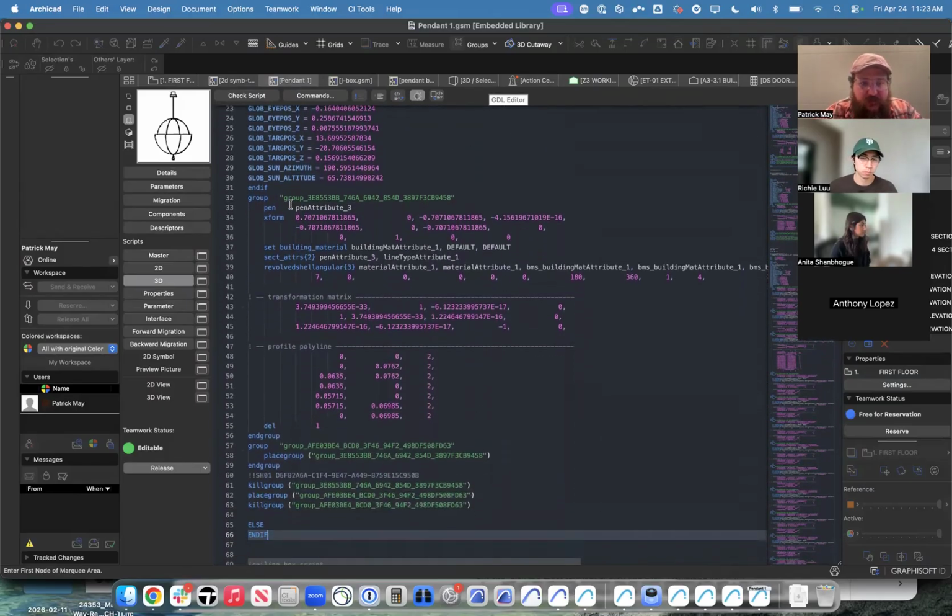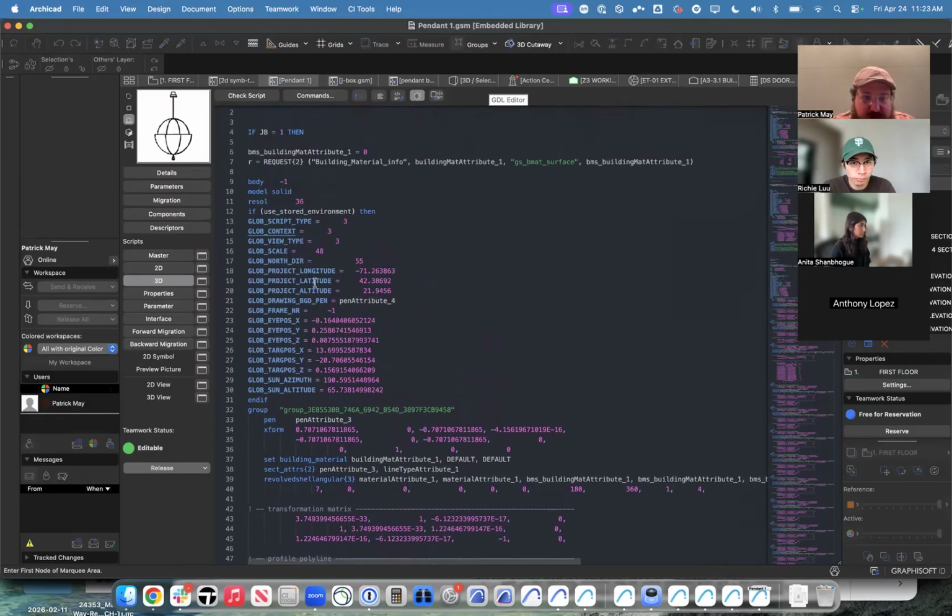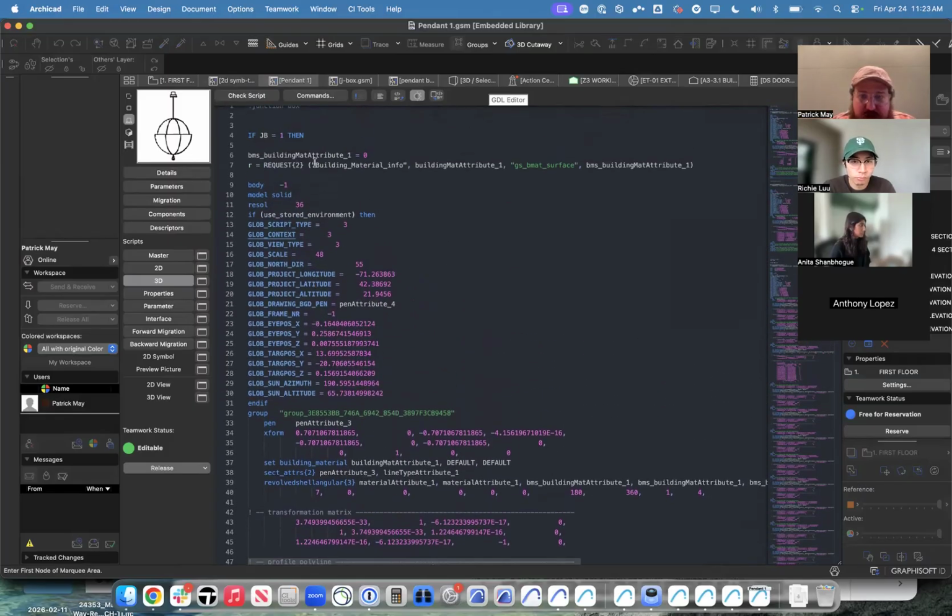So I'm going to look for the material parameters, not the, there's building materials and materials. Technically, materials are surfaces. We used to not have building materials, so we just had materials. And because materials go back like 25 plus years in GDL, they couldn't rename materials to surfaces without basically screwing up every object that had ever been built. So it is important to distinguish between building materials and materials. But in here, I'm just looking for the material code.